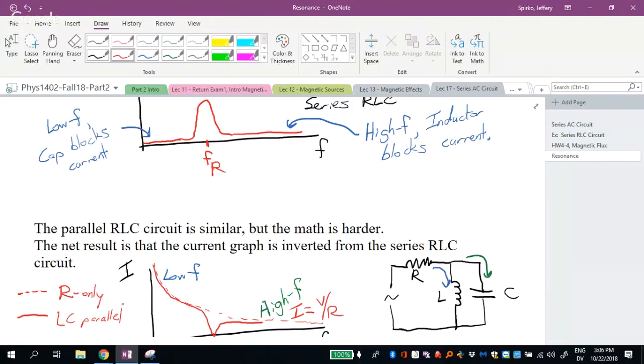Well, if you have a professional soundboard, they can get rid of that sound by tuning a notch filter to that exact tone, and then they can turn the microphone up more, and the person can speak and get heard, but won't make that feedback sound. It has a side effect of getting rid of any singing at that particular frequency, but if the person is just speaking, not singing, it doesn't matter so much.